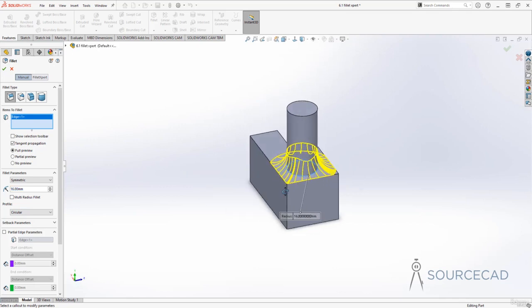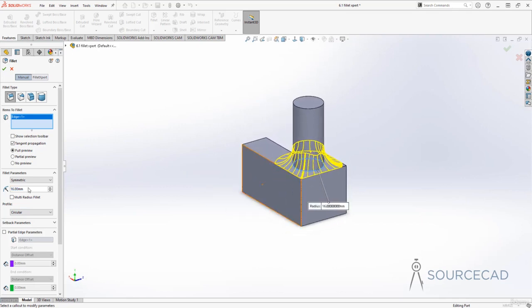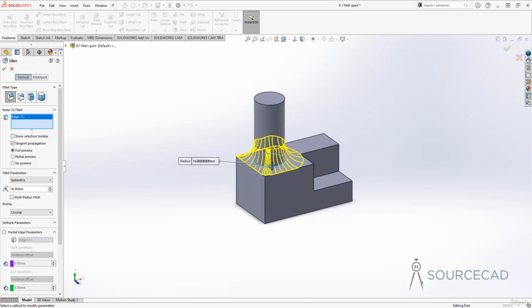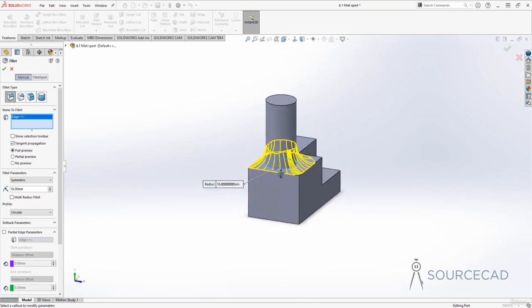Okay. So by default, a fillet radius of 16 is added here. You can apply any other radius if you want to, but I'll just select the 16 mm radius. If you have something else selected, just make it 16 because that's the radius where the changes will be much more visible. Now currently what I'm getting here is a fillet which kind of looks okay. If you see the preview, it kind of looks good and the edges are all maintained.